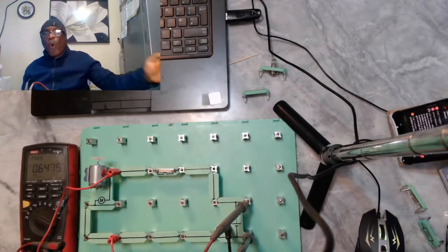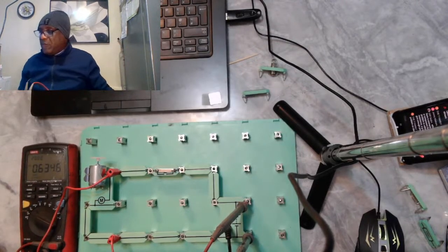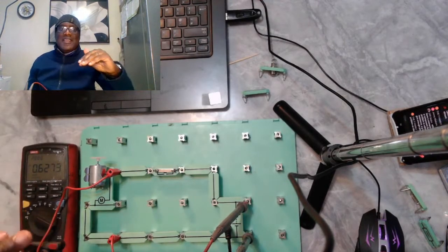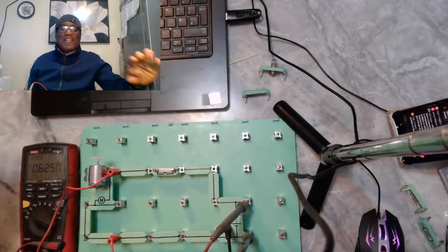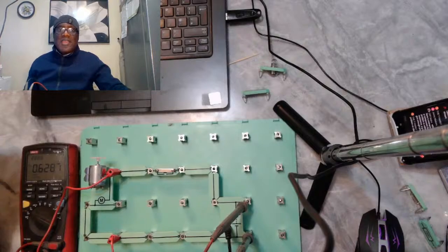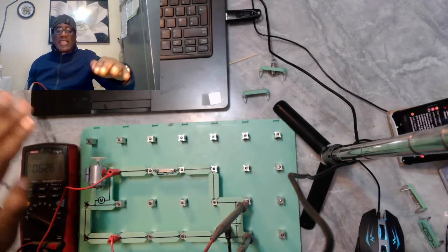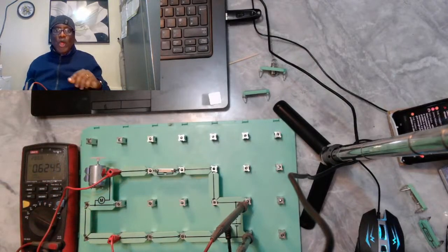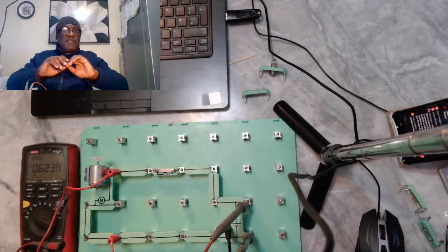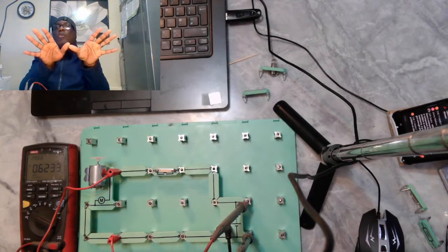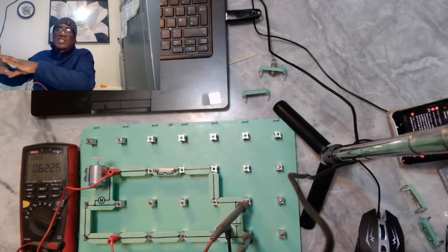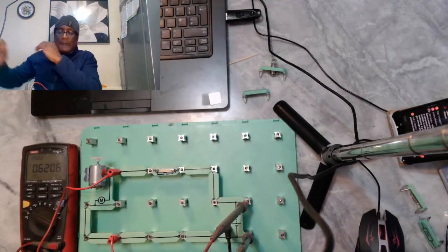Let me give you an example. You could be working with a 5-volt reference. This is another thing that is difficult for technicians to diagnose. The 5-volt reference tree could have 5 or 6 sensors all connected to this one 5-volt reference, and you could have another 5-volt reference that has maybe 3, 4, or 7 sensors.